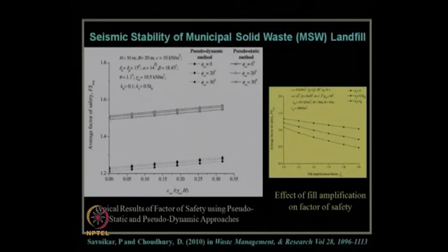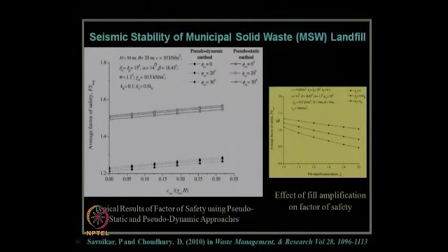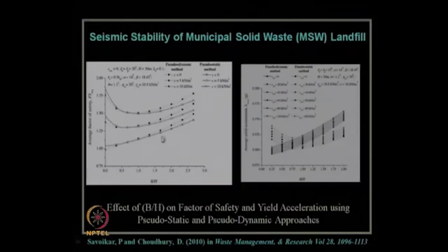So, as we have already learned from the ground response analysis, equivalent linear ground response analysis for MSW landfill, there is always some amount of seismic amplification. So, one needs to consider this amount of amplification when designing the MSW landfill for the stability of the slope in terms of translational failure or rotational failure like this, and then factor of safety and yield acceleration need to be estimated. Some more results of factor of safety for both pseudodynamic and pseudostatic results